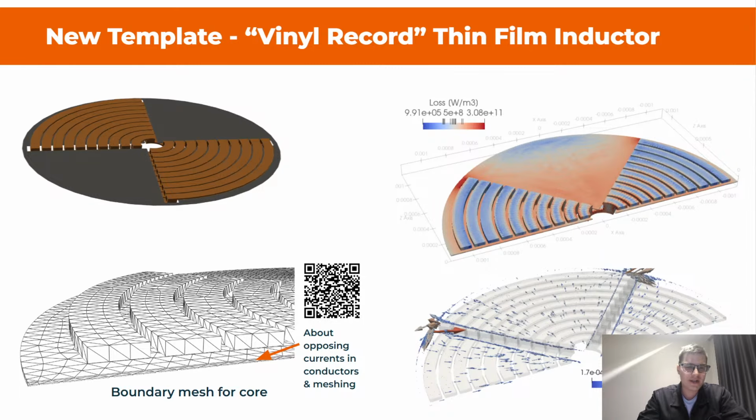So the real name for those components is thin film, and basically the idea is that those are future inductors, future transformers used in microelectronics that could allow them to work in a very high frequency range very efficiently. And thanks to a very thin core and very high saturation flux, they could be quite efficient. So there are a few tricks that you need to keep in mind when you are modeling such thin film